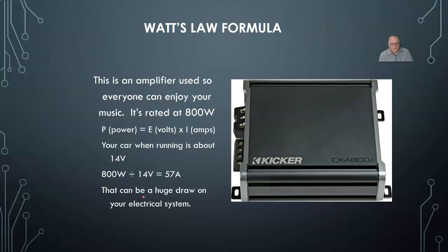Now, on your car with a 120, 130 amp alternator, and you have your windshield wipers on, your blower motor on high, your seat heater on, the rear defogger on, and then you turn this amplifier on, you're going to exceed the output of your alternator.